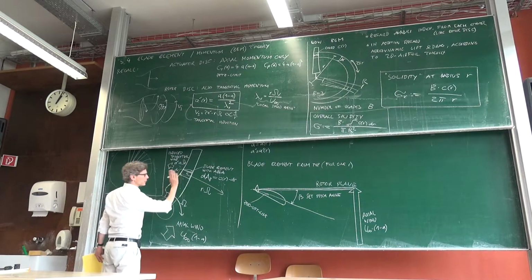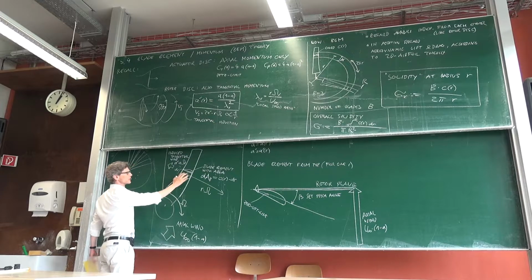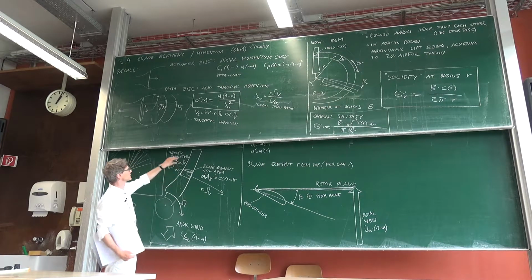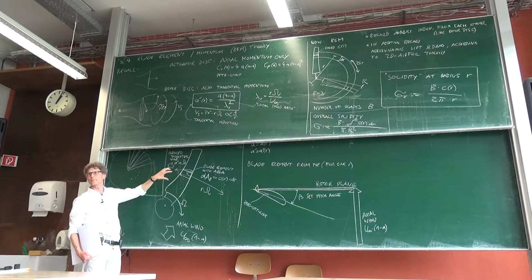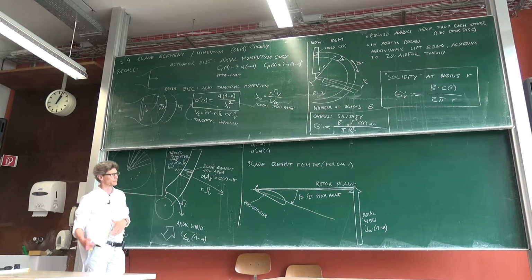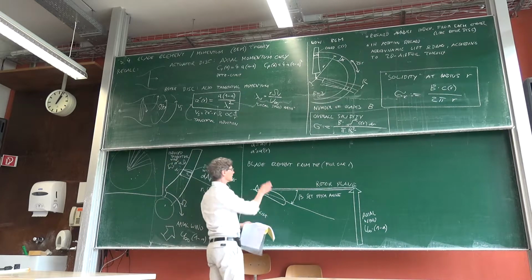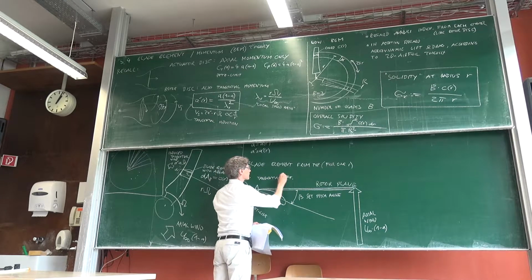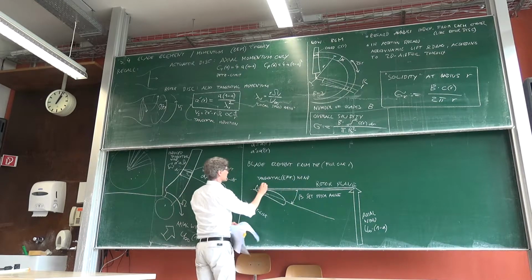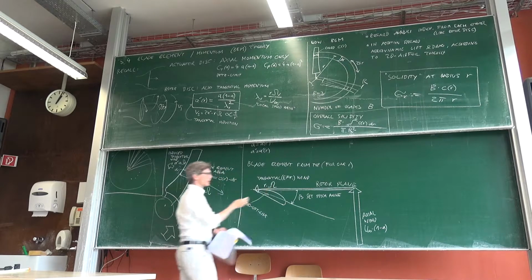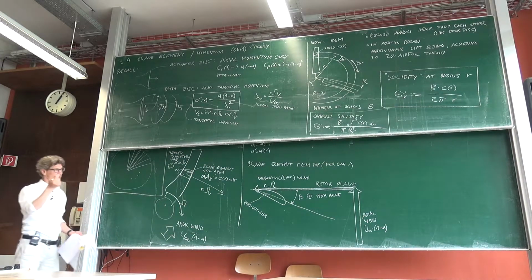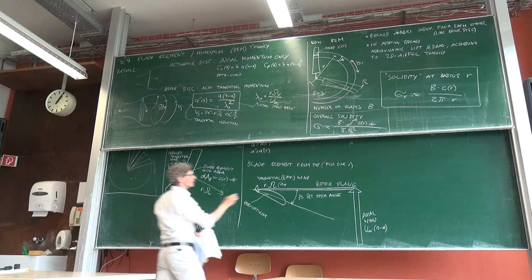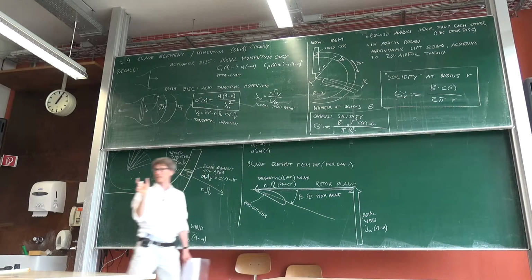The effective wind is what I'm interested in, because I'm now sitting on the rotor blade, right? So on the one hand I see my speed of motion, but then I also see, in addition, the induced tangential wind, because it's making the wind that I feel in this direction a bit stronger. So I call this the tangential effective wind. And what was it? It was R times omega. Without any correction, if there would be no tangential induction, then this would be it. But because we have this extra induction, we get a (1 plus a prime). It's not minus, but plus, because...